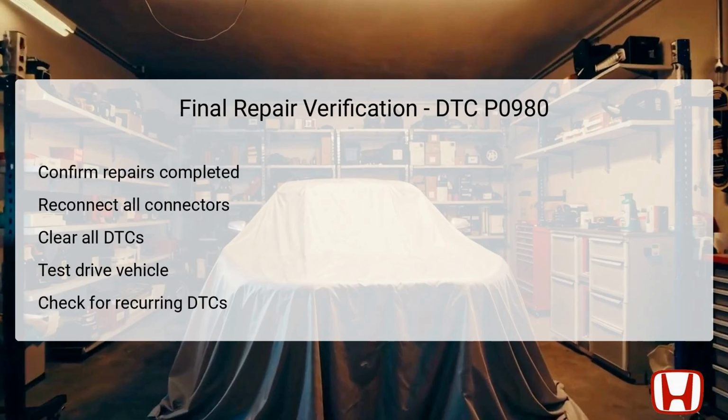And final verification of repairs is crucial after addressing DTC P0980 to ensure all issues have been rectified. Confirm that all repairs associated with the wiring, solenoid, and any identified components have been completed successfully. This includes reconnecting all connectors to restore proper electrical functions fully.